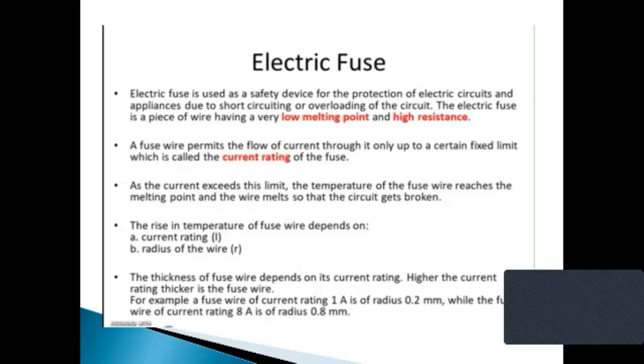The rise in temperature of fuse wire is dependent on current rating and also the radius of the wire. The thickness of fuse wire depends on its current rating. Higher the current rating, thicker the wire. If the current rating is lower, thinner the wire.